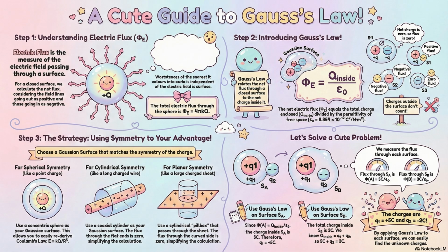It is, and they have mechanical flaws, too. They exhibit the piezoelectric effect. They can literally turn electrical ripple into audible noise. They hum. That's microphonics. And I heard they can crack easily. They are very brittle. Any board flexure, from assembly or even rough handling, can create microscopic cracks. And unlike a failure that creates an open circuit, these cracks often lead to an immediate and permanent short circuit.